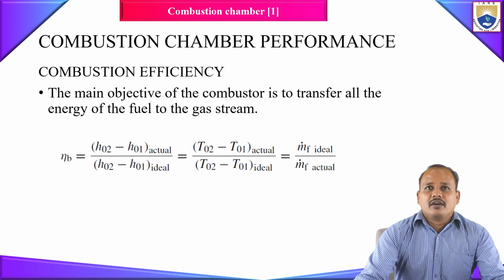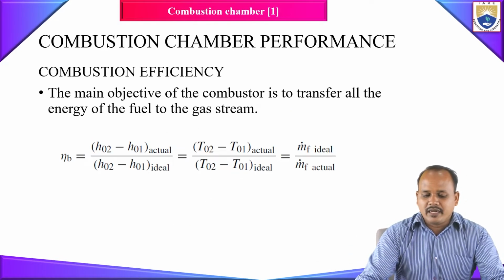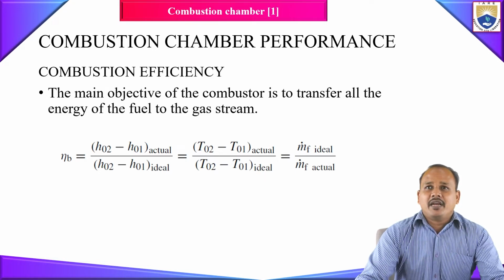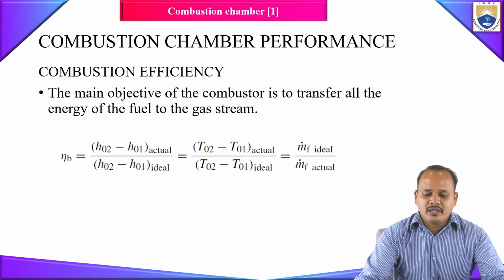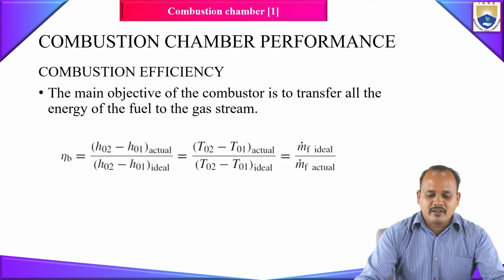Next one is the combustion efficiency. So what is this combustion efficiency? It is how effectively, when I do the combustion, I transfer the energy inside the fuel into the incoming airflow. So we are heating, right? Basically, by doing the combustion, I'm increasing the temperature of my flow. Combustion efficiency is the enthalpy rise during your actual process divided by the enthalpy rise during your ideal process.